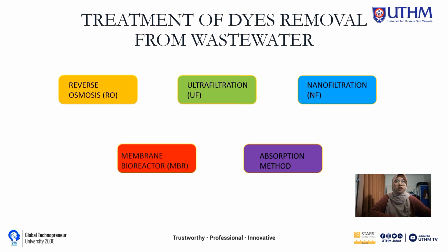Nanofiltration is a pressure-driven membrane process that lies between ultrafiltration and reverse osmosis in terms of its ability to reject molecular and ionic species. NF membranes, unlike reverse osmosis membranes, can operate at lower pressure and provide selective solute rejection based on both size and charge.